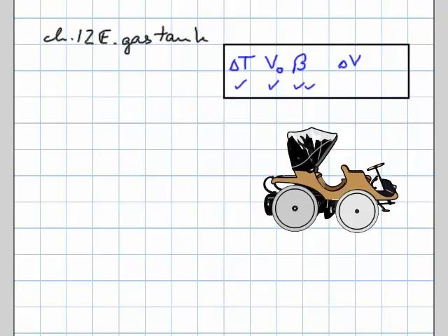So that means actually that the expansion of the gas tank itself is rather negligible compared to the liquid, the gasoline itself, and we'll see that later when we subtract one from the other, that it won't have mattered as much. Okay, so here is for the gasoline, and it says delta V equals the beta for gas times the original volume of the gas,